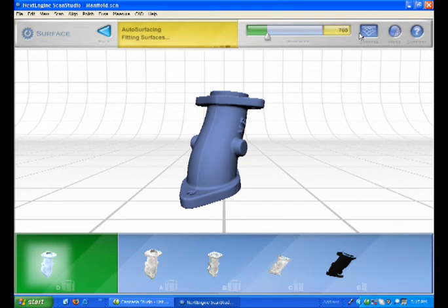What we've done with this in Scan Studio Pro is we've offered the ability to very quickly get to a NURB surface. You'll see that in the translation from an STL file or a mesh file to an IGES file, we still maintain a lot of the detail, and that's a key point, because the translation accuracy is typically around 0.1 mm or less when we go from our NextEngine mesh file, the SCN file, to an IGES file. We'll see the results here.